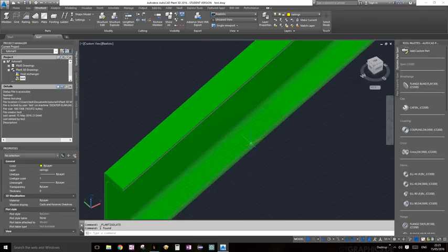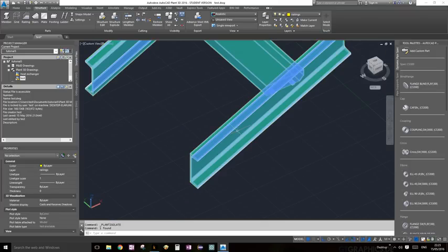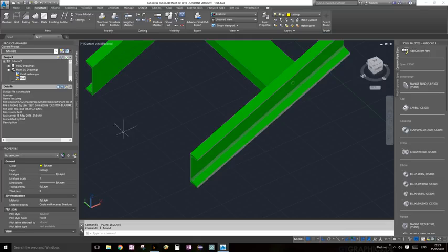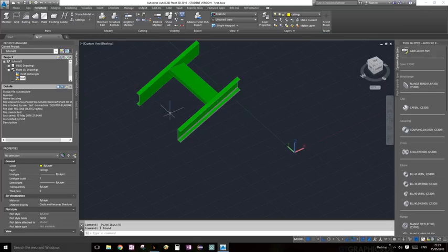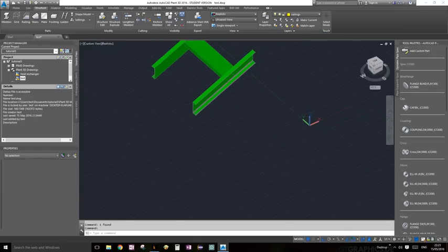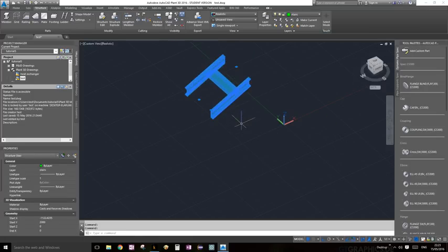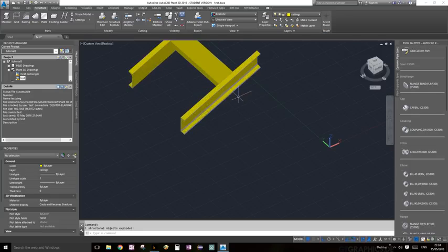Now it's nice. Now you can kind of see where the ground comes in, where the grid comes in there. So what we're going to do first, let's select it. Make sure that you actually draw your railings before you do this, because we're going to explode our little stair right now. And now it has been exploded.